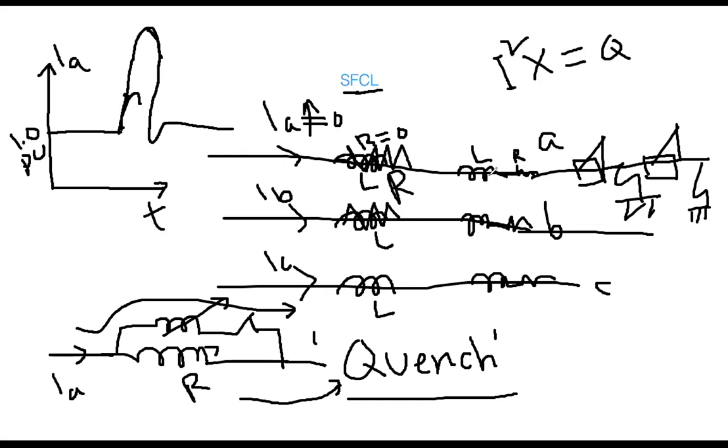But I'm talking about this SFCL during normal condition, because it has even a small value of inductance, it forms I square XL. Because these are the AC lines, of course, so they have the frequency. So XL means 2 pi FL, whatever the small inductance, it will have some reactance. And that causes some reactive power loss. So therefore, that is one drawback.